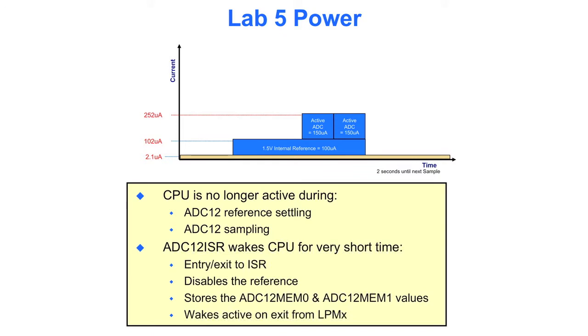So you can see we've again gotten the majority of the time down to 2.1 microamps, but now our maximum here is somewhere around 252 microamps. This is about as far as we can go to minimize the power consumption for this application.